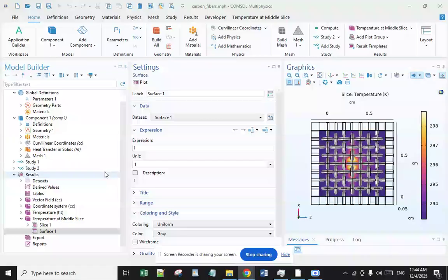The main issue in the measurement of thermal conductivity is to account for the contact resistance. Standardized devices have been used for the measurements of the transverse and in-plane thermal conductivity respectively. They both include two samples sandwiched between a central thin heater and two outer heat sinks. A known heat flux is applied and temperature is measured at the heater and each heat sink. From these values and the dimensions of the samples, the thermal conductivity is determined according to Fourier's law.